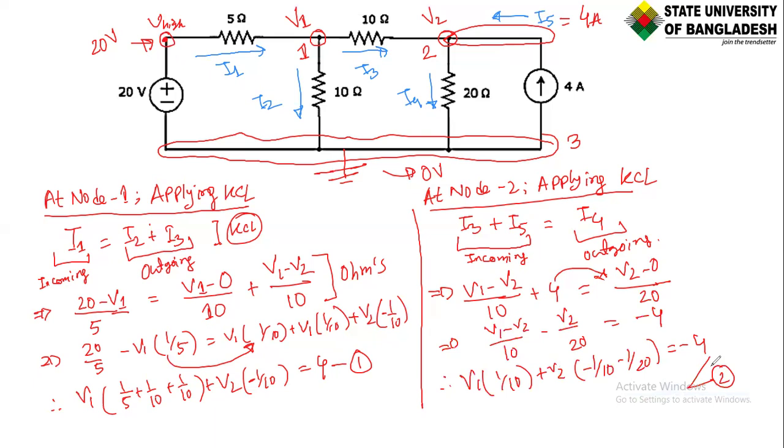One thing is very interesting that you have to understand: how many nodes there are. There are actually 4 nodes. Already one voltage you know. So there are 2 unknown voltages, and that node's voltage you know. Therefore, since 2 unknown voltages, you will find 2 simultaneous equations with 2 unknown variables, V1 and V2. You have to find them out.